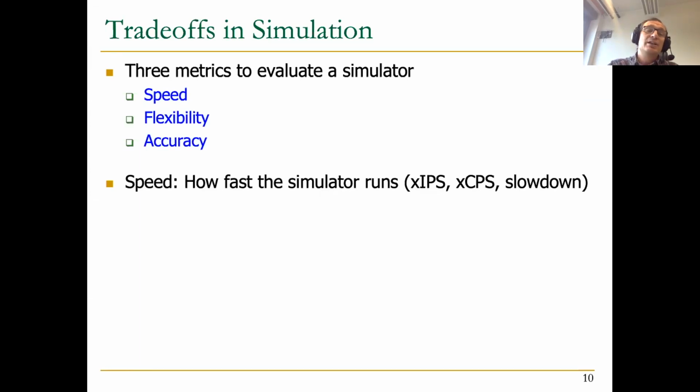And underneath, you also need a timing simulator, where you actually model the timing, energy, costs, etc., of different design decisions that you make. So these two pieces are very different: functional simulation and timing simulation. Normally, if you want a good simulator, you need both. So far, I've been talking more about the timing simulator, but keep in mind the functional simulator is also very important.